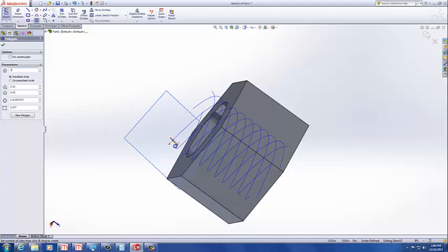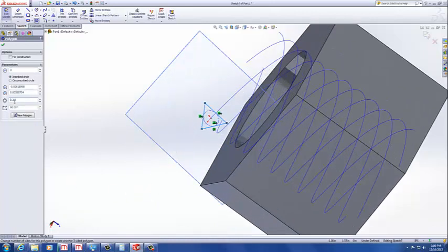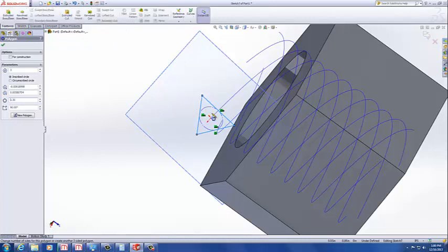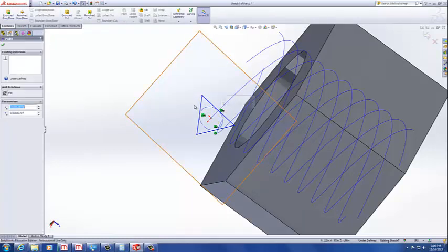So I'll draw a triangle here, and I'll just make this an arbitrary 0.2. Actually, that seems a little small. Let's make it 0.3 for this example. Now, you're going to have to anchor this piece. So, go to, oh, no, we don't want to draw a triangle. Go ahead and select this point, and you're going to want to anchor it. Then you're going to want to anchor this circle. There you go. So now they aren't going to be able to change.